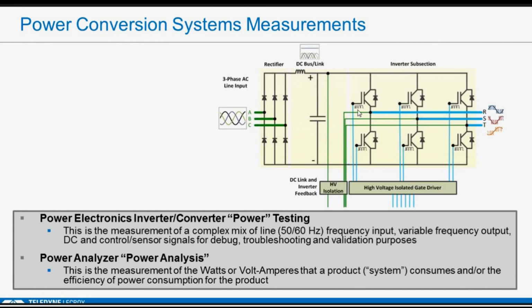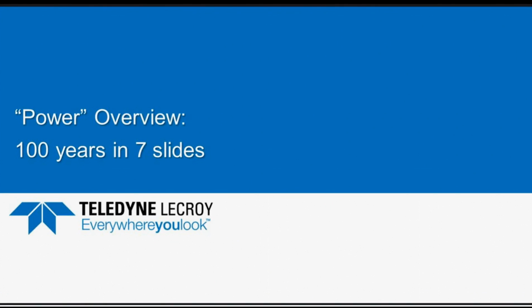And then from that, it uses that DC signal and chops it up using pulse width modulation. And then it recreates something that looks like a PWM waveform. And the more comprehensive systems will have both a positive and negative going excursion, which closely resembles that of a sine wave. So that's the focus of our discussion today, this particular type of system.